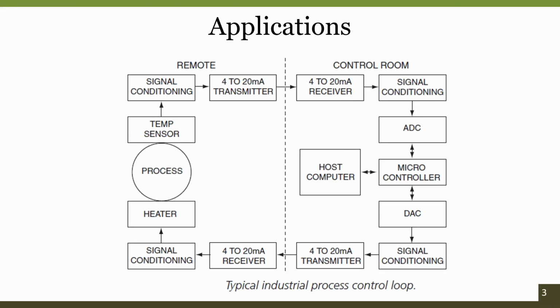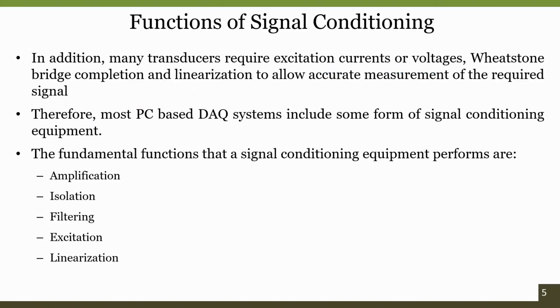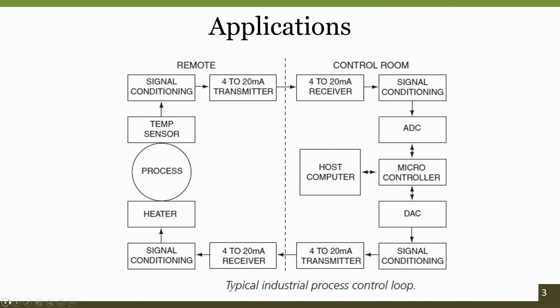The reason they use this is that your sensor may be remotely located from your digital platform or the analyzing circuitry, which in this case is a microcontroller. When we directly transmit the signals from the output of a signal conditioning circuit, which is in the form of voltage, to an ADC over a cable, due to the resistance offered by long cables, there will be a drop of voltage, right.